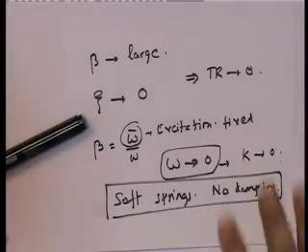That means you need to put the machinery on soft springs with no damping to ensure that very little gets transferred to the floor. Now, this is where I am trying to solve what problem? The dynamic problem. But what other problem do I have? Note that if I make the spring too soft, what happens? The machine has weight, and if I make the spring that soft, the spring is going to bottom out purely because the weight itself takes it down. Soft spring means what? Very flexible spring. If I have a particular weight and a very flexible spring, it is going to sit down.